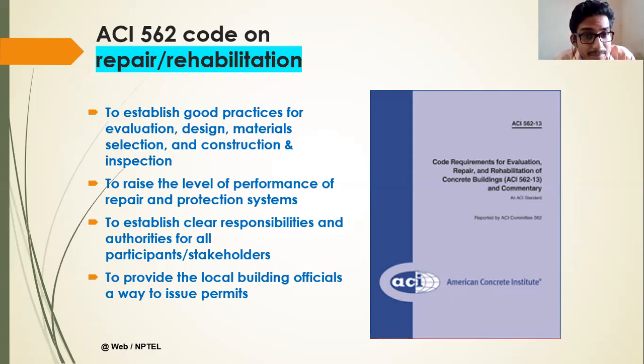Evaluating the problem is very important, and based on this evaluation result you have to go for design. Design here means the repair methodology, material selection and other things. It also aims to raise the level of performance of the repair and protection system, and to establish clear responsibilities of all authorities or participants. Who all the participants are and what their responsibilities are is also mentioned in this document.